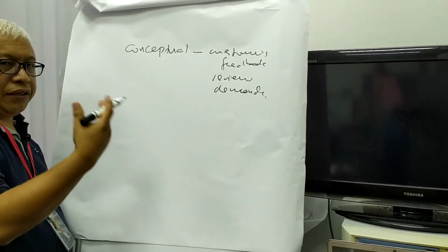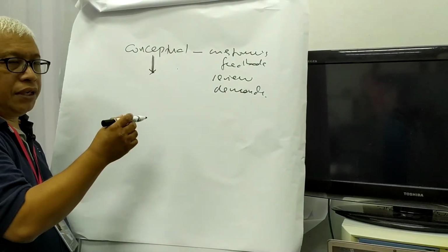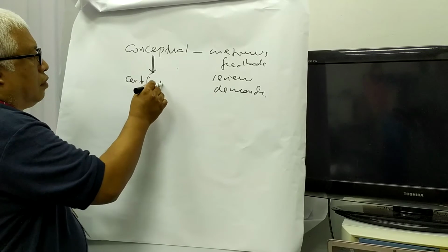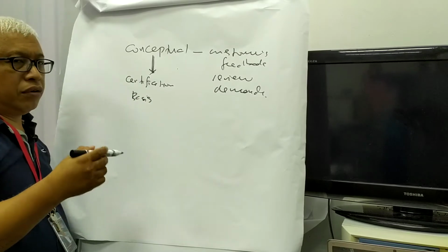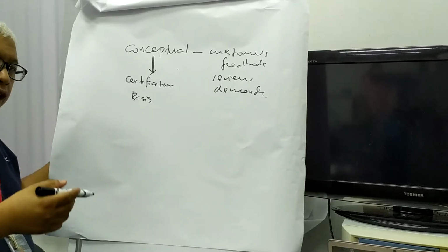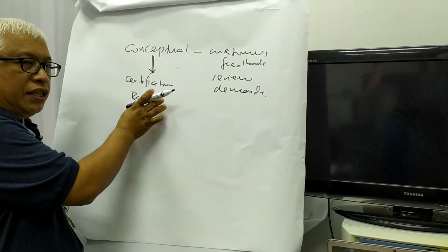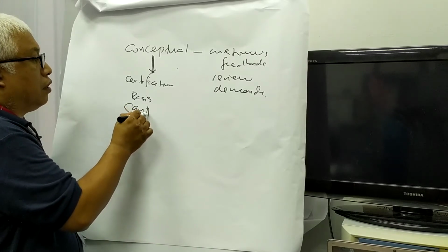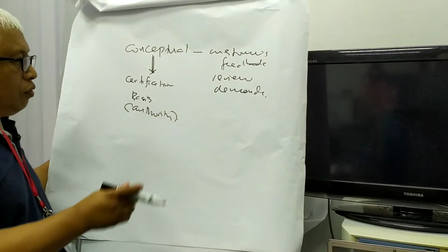Once we have the conceptual design and the marketing and sales department say that it is a sellable product, potentially with customers, then we go for the detail, which is we need to establish the certification basis. How are you going to certify the aircraft? How are you going to certify the product? It must be certified, and before you go for the certification, you have to come up with the certification basis, and this requires negotiation with the authority. You need to negotiate with the authority what will be the set basis.